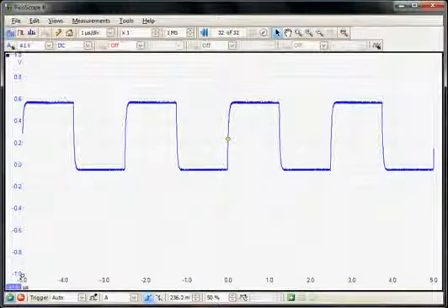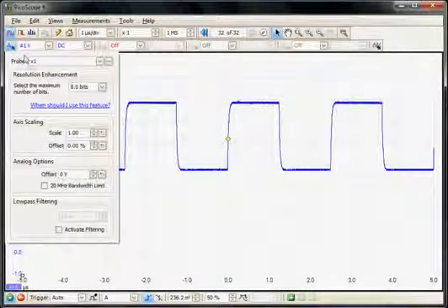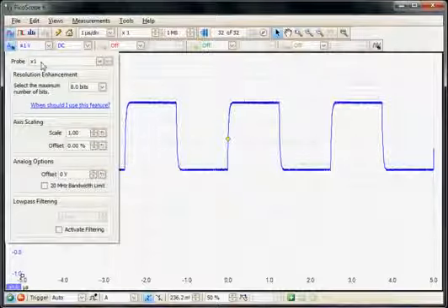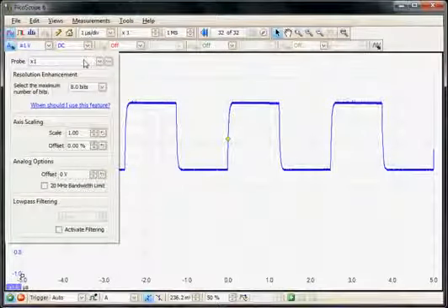The PicoScope has a channel options menu which allows the user to define the scale factors for any particular probe that has been connected to each of the channels. This could be channels A, B, C or D. So under the channel options menu we can define the probe functions or use a standard probe function from the